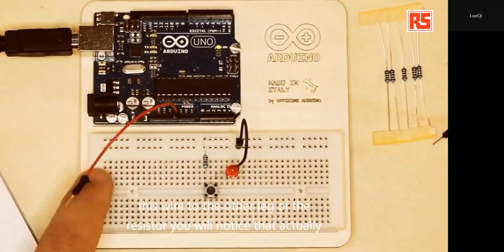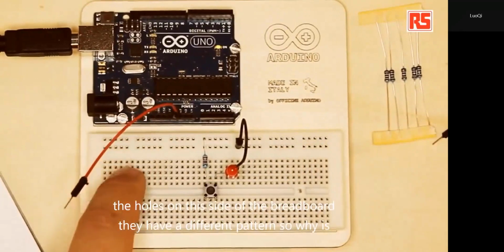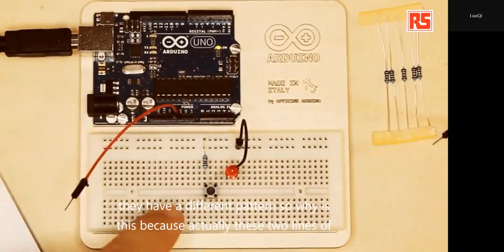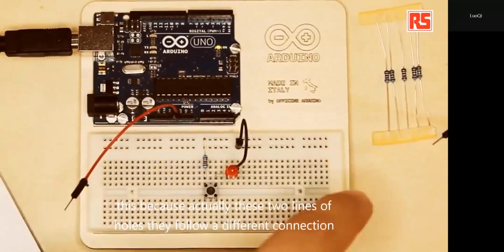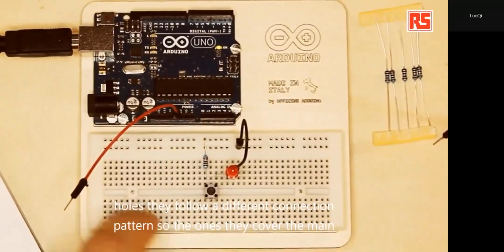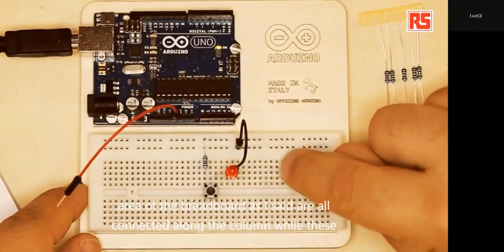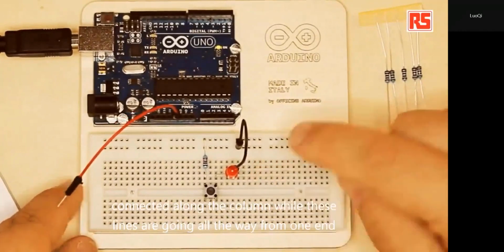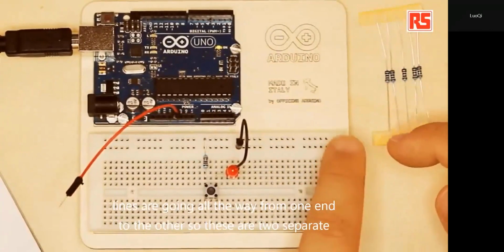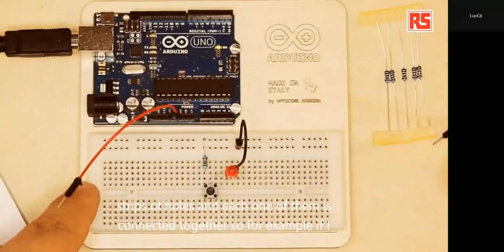You will notice that the holes on this side of the breadboard have a different pattern. So why is this? Because these two lines of holes follow a different connection pattern. The ones that cover the main area of the breadboard, as I said, are all connected along the column, while these lines are going all the way from one end to the other. So these are two separate strips of holes, and each one of them is connected together.